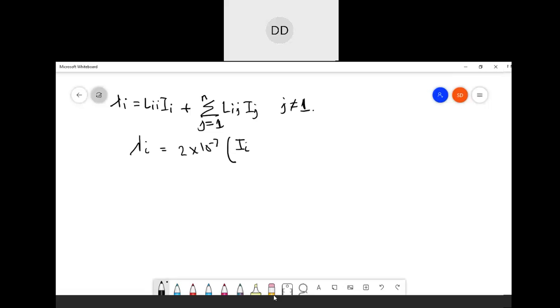I already told you with respect to the first value our GMR, that is 1 by r1 dash, wherein r1 dash is 0.7788 times the radius of the conductor, where r is the radius of the conductor, plus for the secondary part, in case of Ij, we have the geometric mean distance, which I mentioned, and again J is not equal to I. So these are some prerequisites before we move to the inductance calculation of a three-phase transmission line.